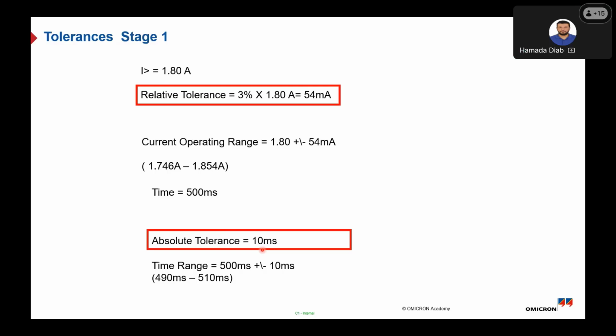Okay, so it can be automatically assessed by the Test Universe software. But if we are using a standalone or a generic test module such as quick CMC, ramping, pulse ramping, test sequencer, and so on, you have to select the greatest tolerance limits, okay, to allow Test Universe to make a correct and precise assessment of the test results. But if you are working with a dedicated test module such as the overcurrent module, distance module, advanced distance module, or differential modules, the Test Universe software will select whichever is greater directly. You just have to import the relay parameter setting and start your protection testing.